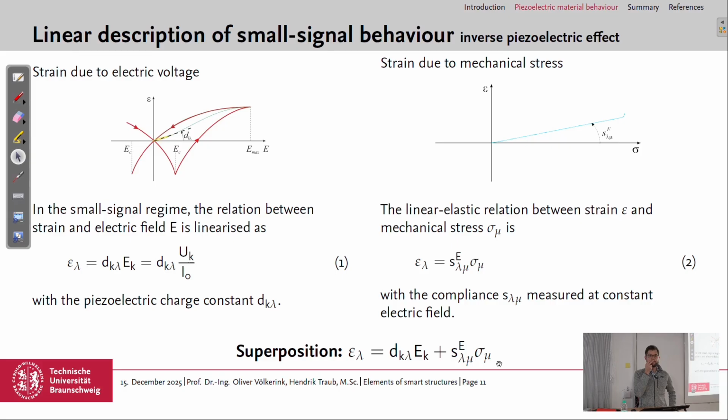What is causing this mechanical stress? For example, in the application, the external loading. But isn't the electric voltage itself causing the inverse piezoelectric effect, like electric voltage causing the stress? So they should be equal, right? Why are they superposed? It depends on the boundary conditions, I would say. If you have the piezoelectric material not integrated into a material, and no clamped or blocked boundary conditions, then it could move freely and does not build up any stress.